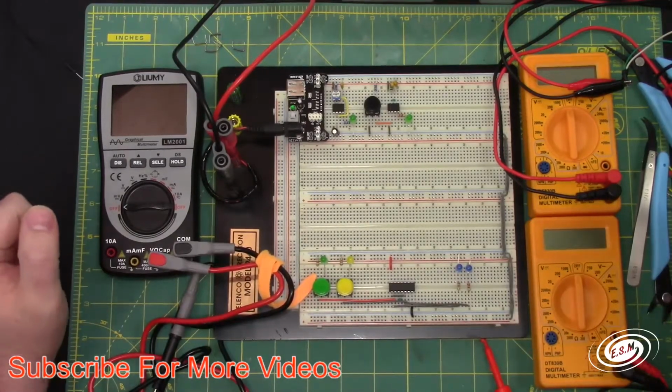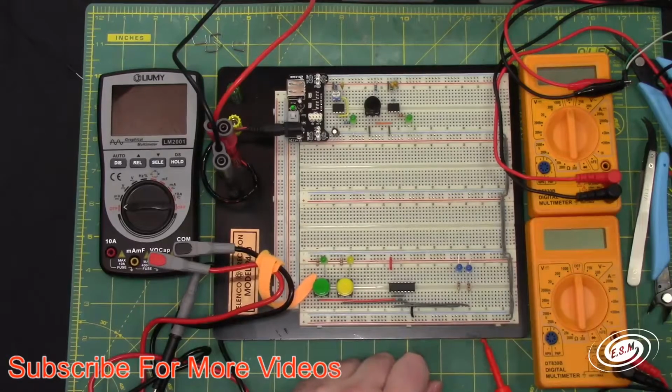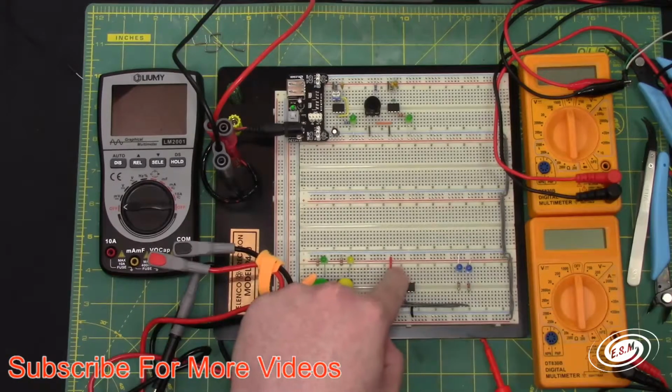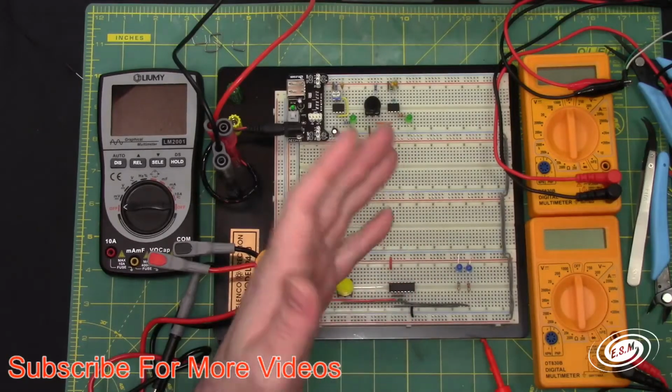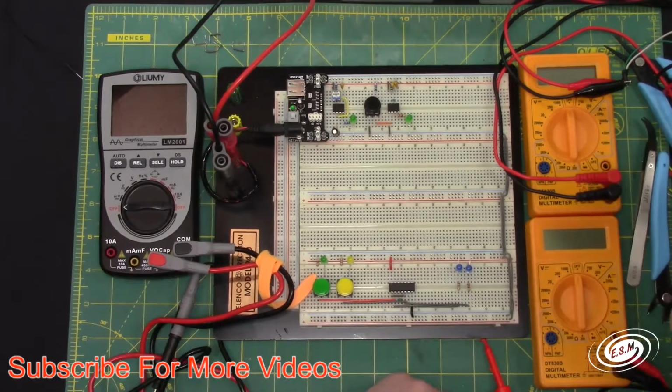So I am using, I'll just look at my notes, a 74LS02. It is a quad two-input NOR gate. The inputs of this are on pins 2 and 3, and the output is on 1. Then it is pins 5 and 6, output 4, and then it's the same thing on the opposite side. I didn't write that down because I'm not using that. So, and I got some meters because I want to test some characteristics of the chip.